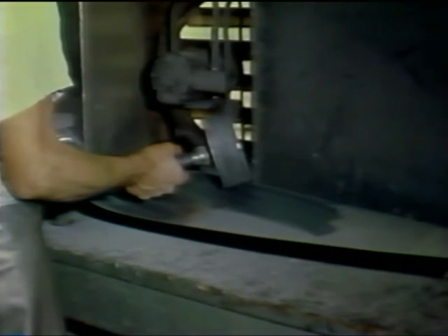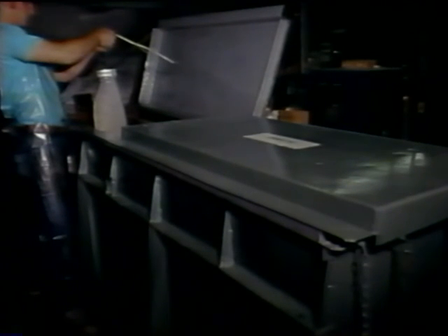Grinding and polishing is the last step in the blade reconditioning. Precision hand grinding removes all corrosion, scratches, and burrs prior to the anodizing process. Close visual inspection is used to detect any small pits and scratches that could lead to blade failure. Anodizing aluminum propeller blades protects them from weather and avoids corrosive buildups that could lead to blade failure.